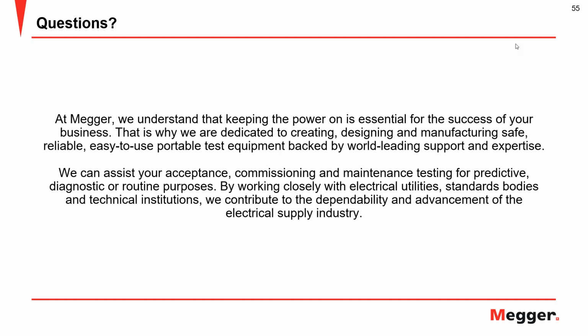Okay. Over to Robert. How do some in-field testing companies claim to detect PD down to 5 picocoulombs on cables and accessories? ICEA S94649 asks for 5 picocoulombs as the limit on cables. Is it the same in the field? Okay, this is an interesting question.